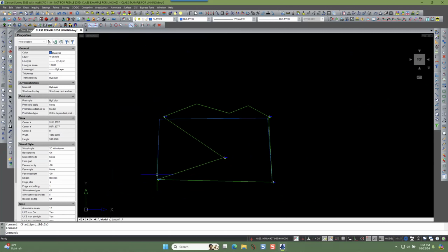But be careful if you do that with the linking on and you grip edit the line work. Be aware whether the linking was on when the line was created. If it was, then it's always going to be linked. You can't just go back and uncheck that switch and now this line behaves as if it wasn't created with the switch.